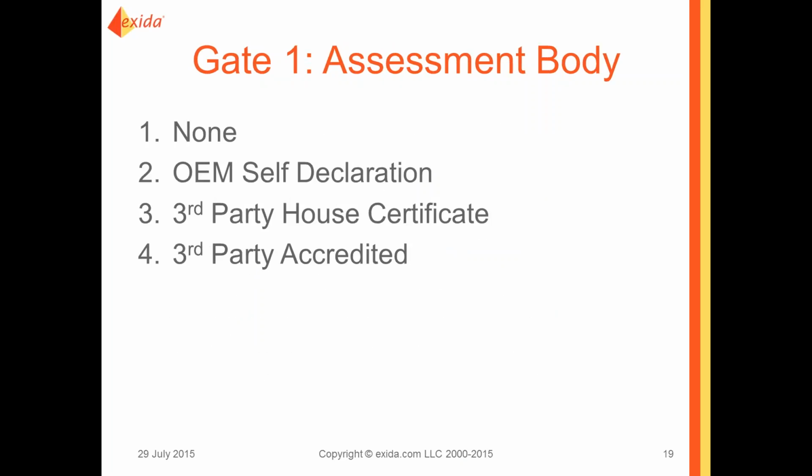Gate number 2 would be who's providing the data or the assessment that that product is suitable for use in a safety system. Sometimes there's no information. Sometimes there's an OEM self-declaration. Sometimes there's a third-party in-house cert, and sometimes it's by an accredited third party. So let's look at each of these.